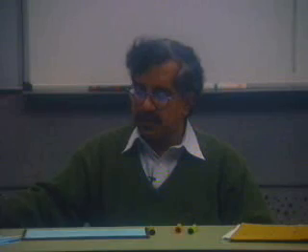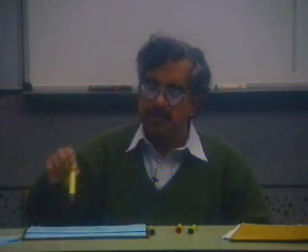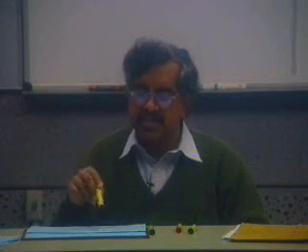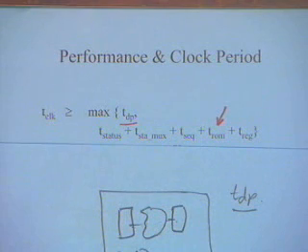So now that gives us the clock period. We will actually improve upon it when we consider the design details of the sequencer. Here I have just abstracted the sequencer as a combinational logic, and I said T sequence is the delay of the sequencer.